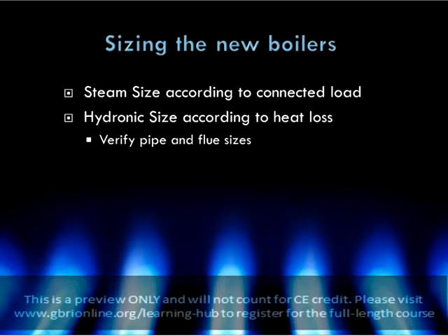They just know that there are cold areas inside that they're trying to heat. One of the other things we find with steam systems is that people will ask, why isn't the radiator heating all the way across? The only time it will really heat all the way across is on a design day, which is usually the coldest day of the year.